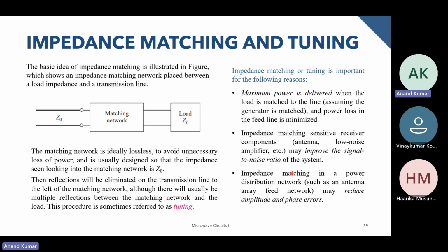So what I'm trying to say is you will need this impedance matching technique to match the impedances at different points in the circuit. And if it is not done properly, there will be phase errors, amplitude errors, noise introduced into the system, power loss, and reflections. So essentially, this is very important. A lot of people initially ignore this, and you might end up with a circuit which is not delivering proper results. And if you don't know about this, you might think that something is wrong in your circuit design, when it is actually the impedance mismatch.